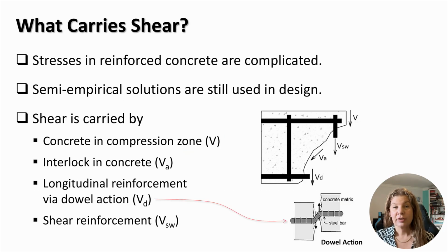The state of stresses in reinforced concrete is complicated. Therefore, semi-empirical solutions are still used in design. Shear in a reinforced concrete beam is carried by concrete in the compression zone, aggregate interlocking in concrete, longitudinal reinforcement via dowel action, and shear reinforcement.